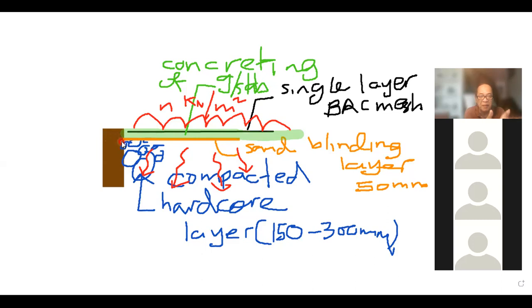We have one ground beam, we have one ground slab, and the ground beam and ground slab are not attached physically. So all loadings on the ground slab are transferred to the soil, and the most problematic issue with non-suspended ground slab is the ground slab settlement.